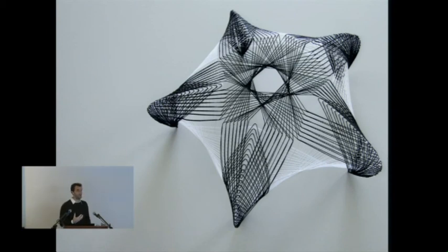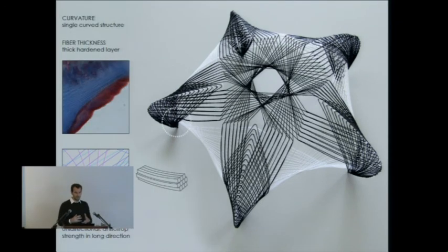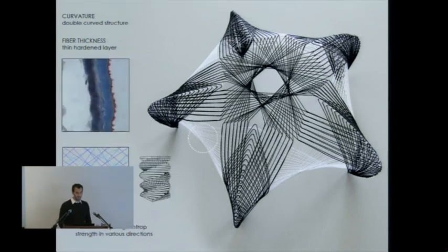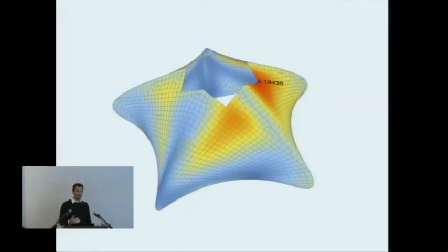So the idea was that we construct a kind of surface using glass fiber, and on that we lay carbon fiber rovings that then are really the load-bearing structure. So for example, you get regions of unidirectional carbon fiber arrangements at the support points and more helicoidal glass fiber organizations at the shell's closed side, which was again iteratively checked through structural simulations.